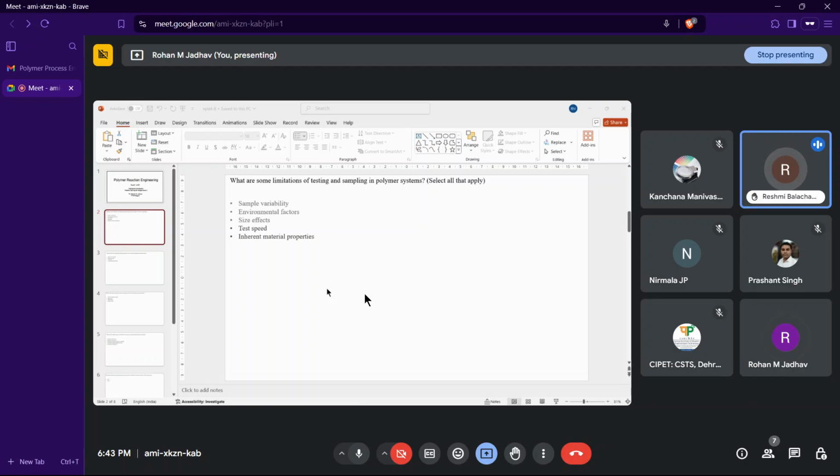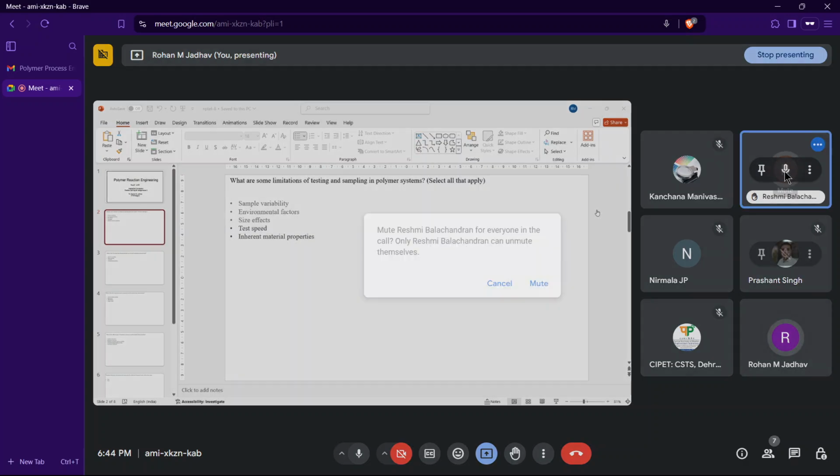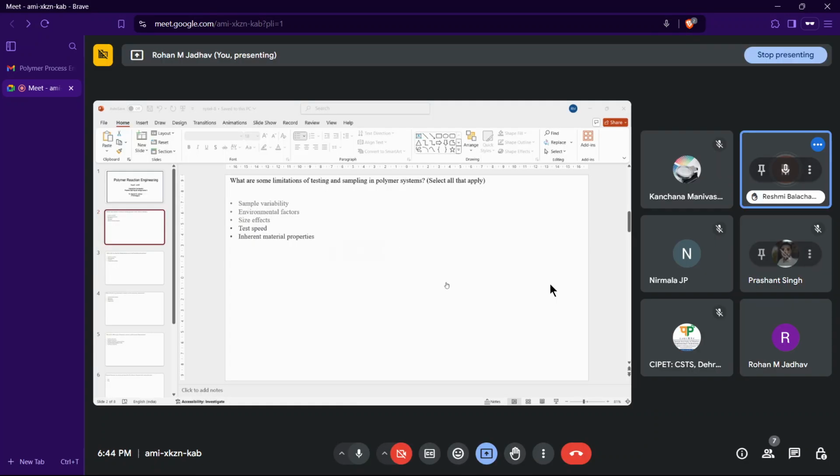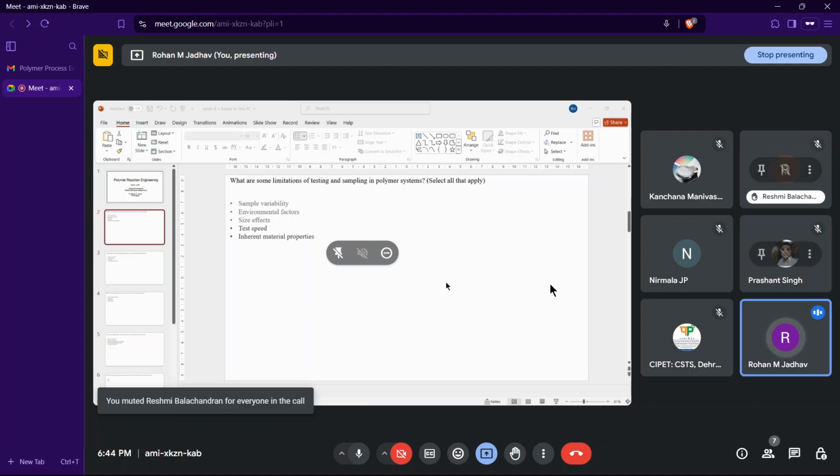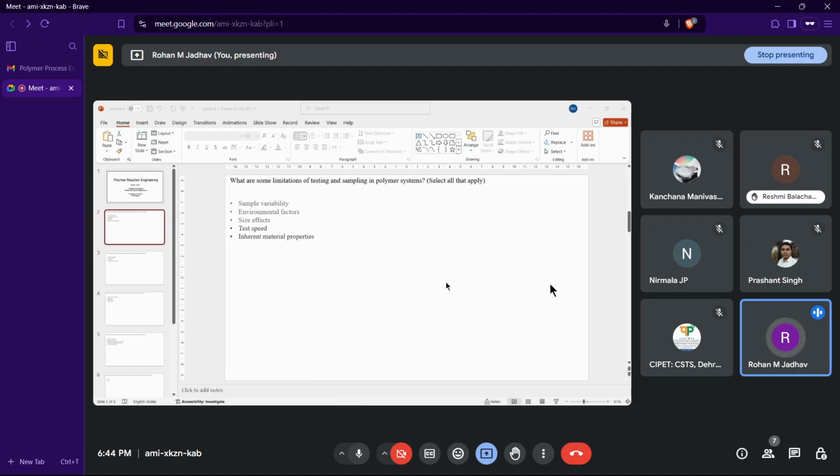Okay, I'll explain why it is there. We were telling that in compression molding, flash will be an error, but injection is not like that. Basically, it will behave in a similar manner. When we are injecting the polymer into the cavity during injection molding, similar to how compression molding provides force and pushes extra material outside, that extra material is flash.